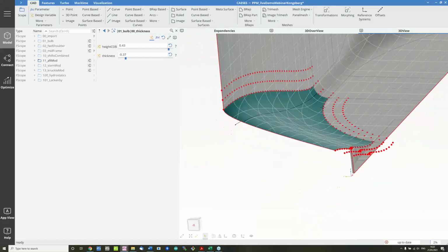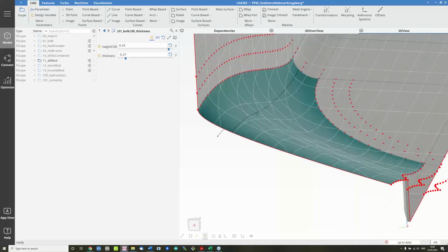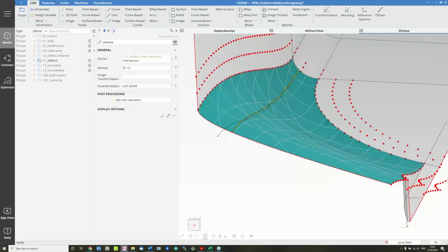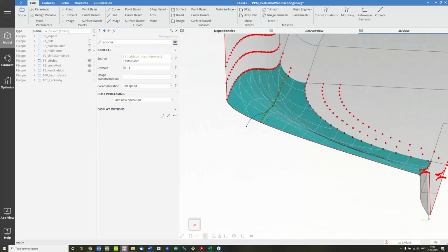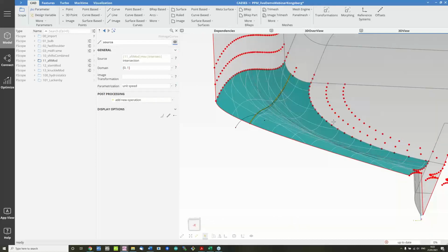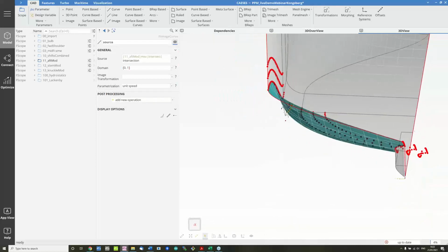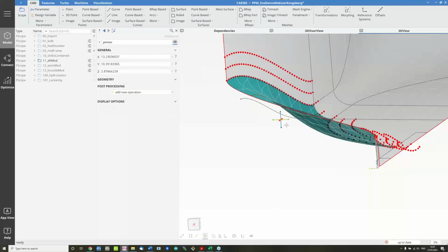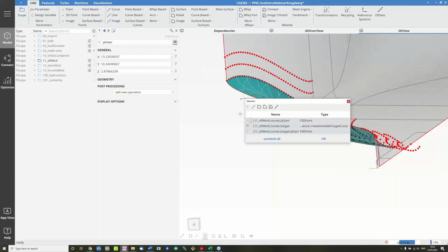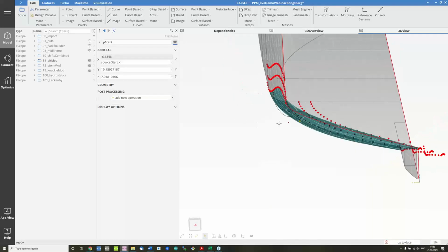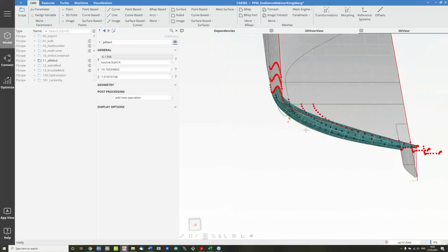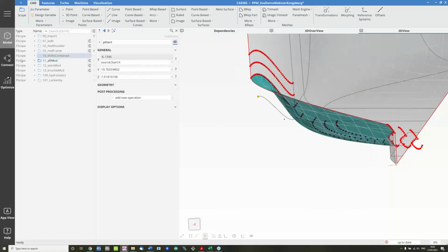That becomes a bit more clear if I explain my first transformation here. I've set up this curve, which is basically an intersection of a plane with my initial shape. And I've set up another curve in space. I can freely control the shape of this curve by moving around these control points. Maybe I want to move this aft point here a little further out. That's totally up to me where to put that curve.